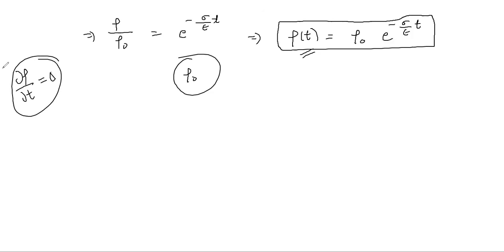Unless this becomes equal to 0, your charge will keep on moving from the place where you have placed the charge on the conductor, whether it's a good conductor or a poor conductor. Depending on the conductor that you are talking about, it may be a very good conductor. If it's a good conductor, then its sigma is going to be large, right? Good conductor means its conductivity is going to be very large. If its conductivity is very large, then the charge is going to decay exponentially very fast, which means that the charge will distribute itself on the copper pipe or copper wire very fast.